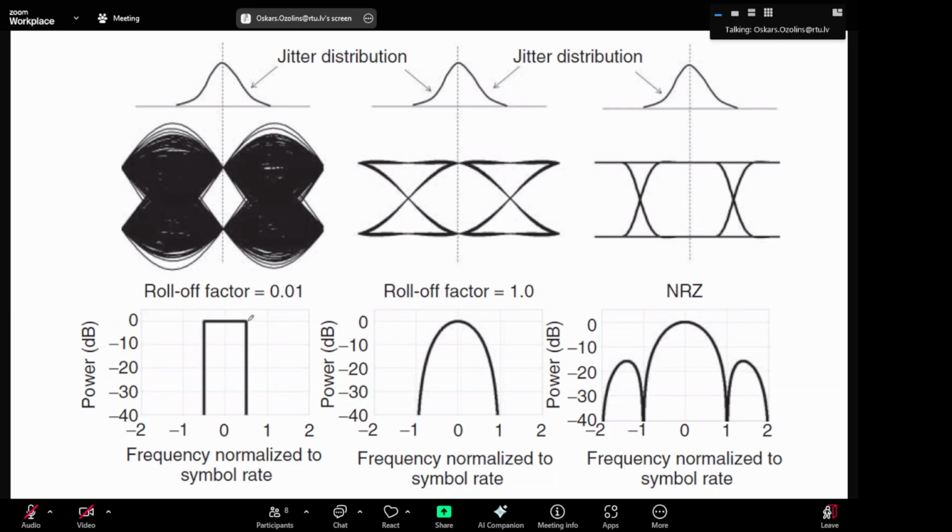So you can pack one more channel here and one more channel here. And basically, you can probably put more capacity with pulse shaping than with non-return to zero signal by using the same band. So at least you can double the capacity if we look at the first zero. If we don't count these, if we count the energy only here, then you can double it with the pulse shaping.